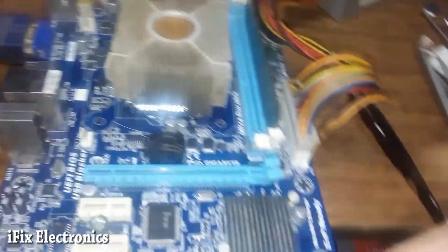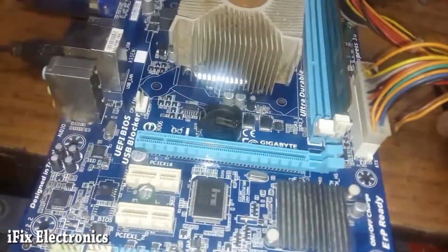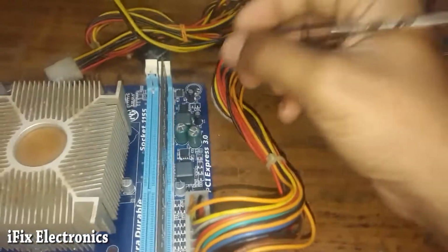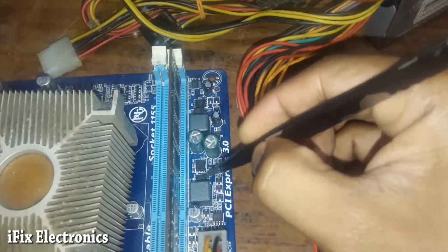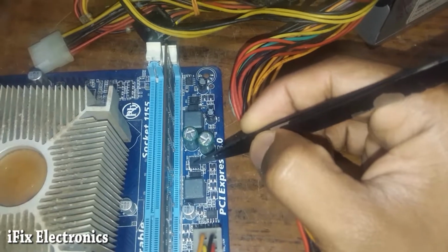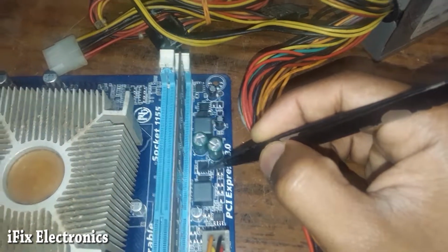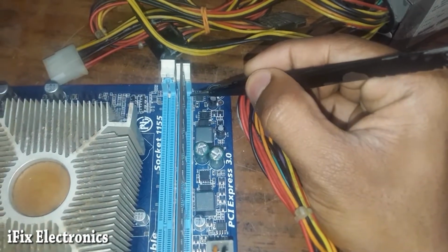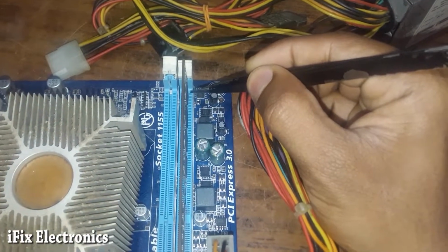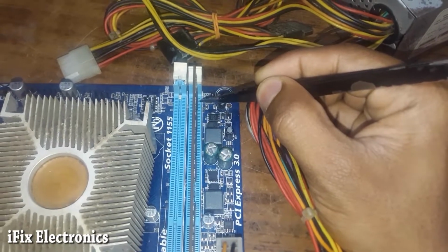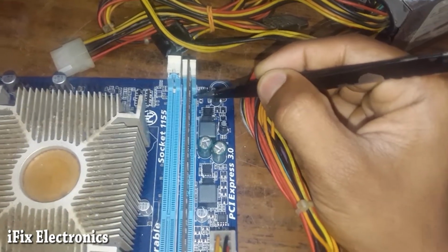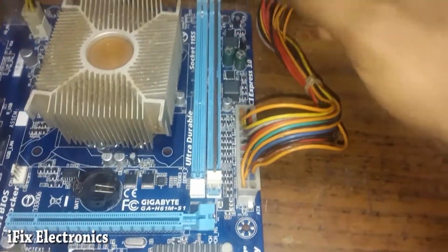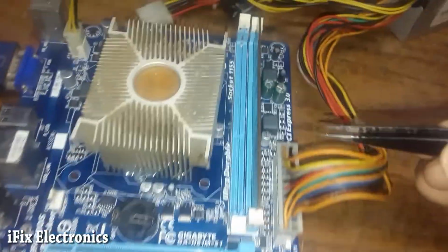Let me check its CPU temperature, which is also quite good, and it's working nice. So let me speak about what voltages you have to check on this motherboard. First, here we have two MOSFET pairs. On this MOSFET pair we have to get 1.5, which is RAM operating voltage. After that, on pin number 120 you have to get 0.75, which is actually RAM VTT. Then check SM clock and SM data. After that, the SPD VDD pin. Those are the voltages which we have to check on the RAM socket.